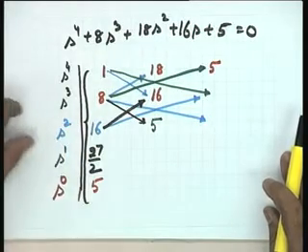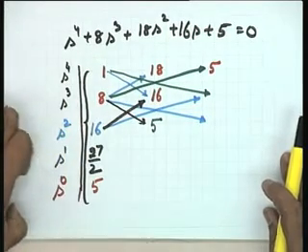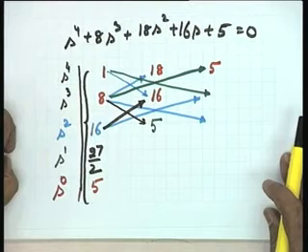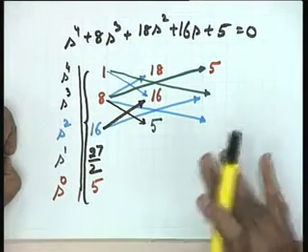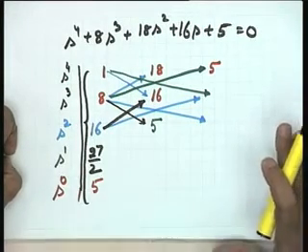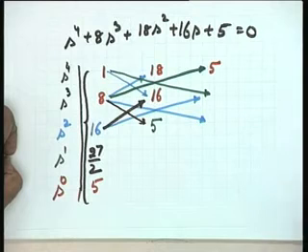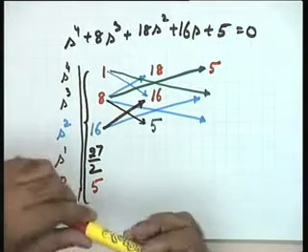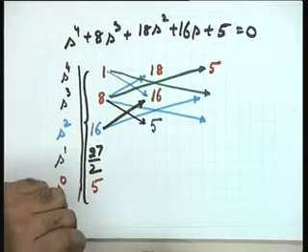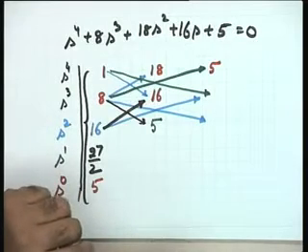It says that if there are sign changes, in that case the system is not stable and the number of roots in the right half plane is equal to the number of sign changes. So, in addition it gives you information on the number of roots in the right half plane.